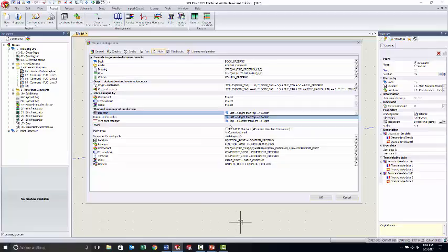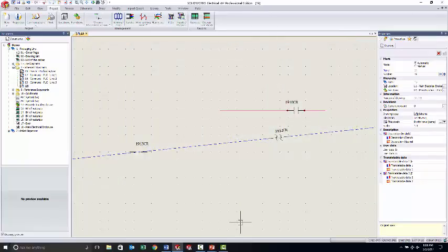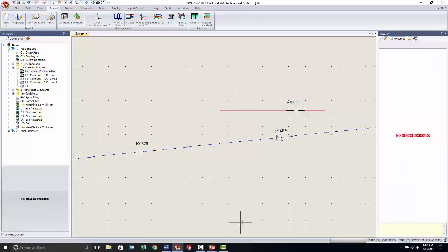But we do let wire numbers do their thing, and they're not based off of a sheet and row position. And so they want to go 1, 2, 3, 4 based on the order of the pairs. Oh, okay. It scans across the entire 11 by 17 sheet. And so you could have wire number 1, 2, 3, 4. Okay, so you're not doing it geographically because we set that up in our title blocks and it works quite well. We are for 90% of this stuff. Right. There's just a few situations where the wire numbers have really no meaning, so we just wanted to go in the order that they appear.